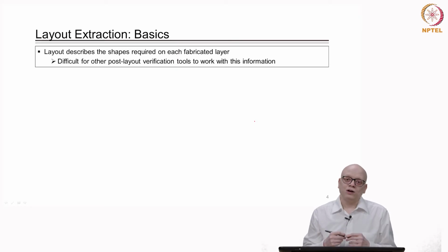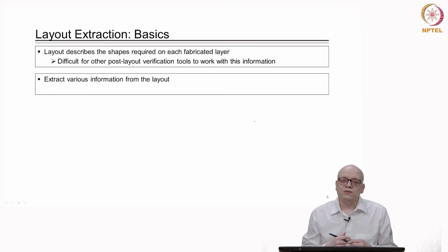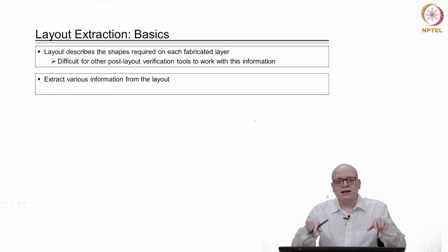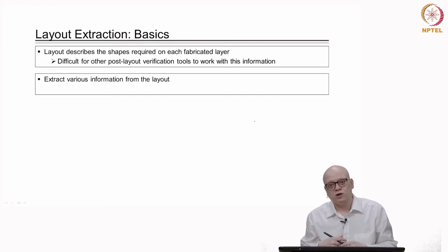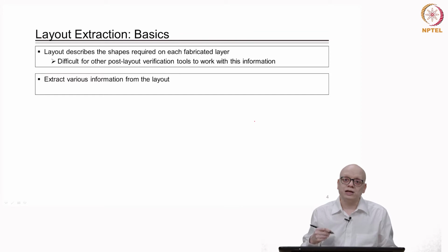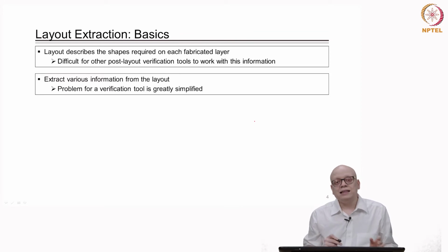Therefore, once the final layout has been created after detailed routing, we extract useful information from the layout that is relevant for post layout verification, and then give it to various tools, for example, tools that do timing analysis, power analysis and other types of analysis.